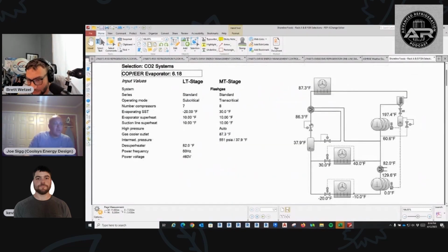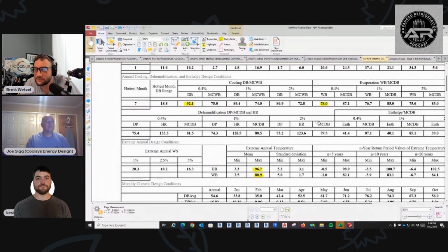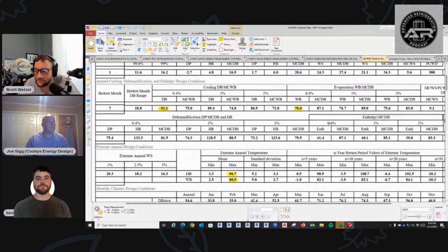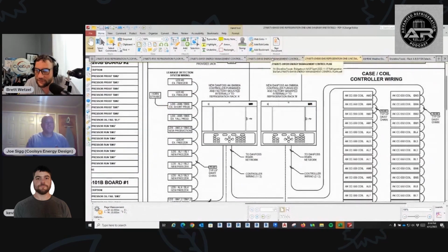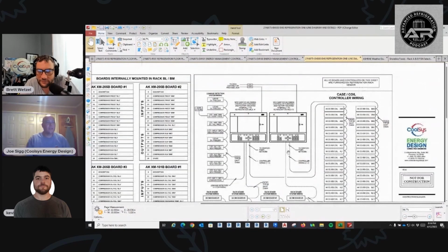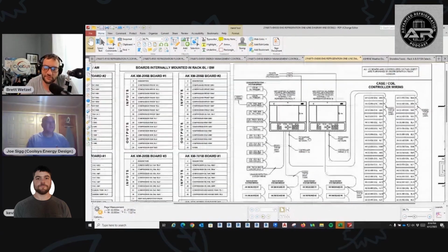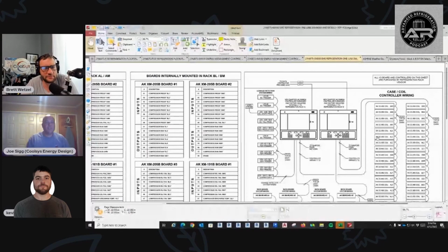So yeah, that's basically the gist of sizing a CO2 system. When it comes to sizing heat reclaim coils, things of that nature, we really rely on the vendor to do that. We'll reach out to the evap coil vendor. Typically we use Ref Plus or somebody of that nature that has a CO2 coil already.